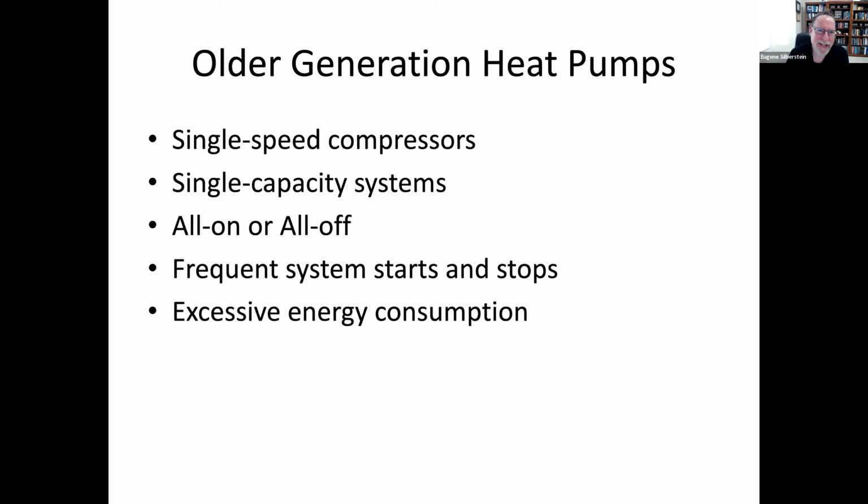Now, with tongue in cheek, I started off saying why people hate heat pumps and why they don't work. Well, we love heat pumps and heat pumps do work. And one of my colleagues had mentioned all heat pumps are created equally and then they're installed. So we do have some challenges, right? Older generation heat pumps, we've been talking a lot about inverters over the last couple of days, but think back to our older generation heat pumps. We had single speed compressors, single capacity systems. They had two speeds. They were either full on or full off. So the system had frequent starts and stops.